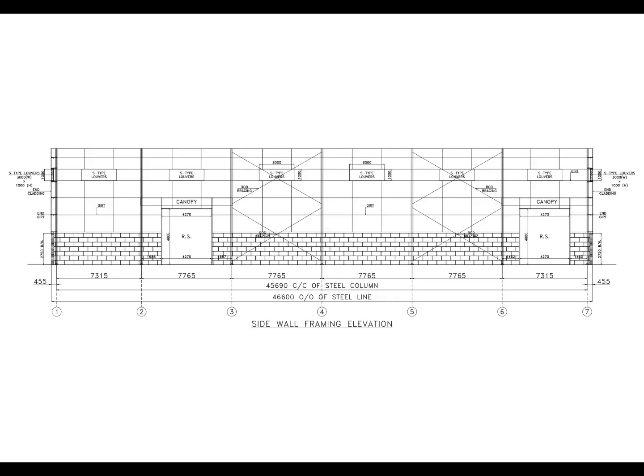You can also see that the Girt arrangement continues across different bays of the building. This means the wall framing is not just one isolated connection. It forms a continuous secondary framing system along the building. But can we identify the same Girts from another type of drawing? Yes. Let's verify them in the frame elevation.